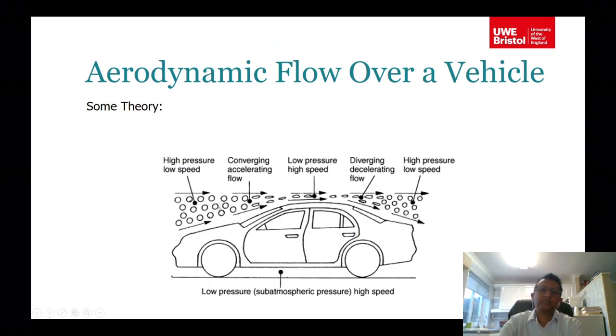This is necessary to understand the aerodynamic flow over a vehicle. Say this is a car, moving in the forward direction. There is a high pressure zone here, so the speed is low here, and then due to the shape of the car, the fluid accelerates over the body of the car.